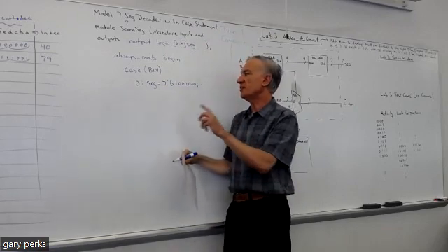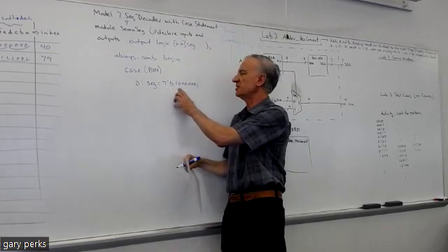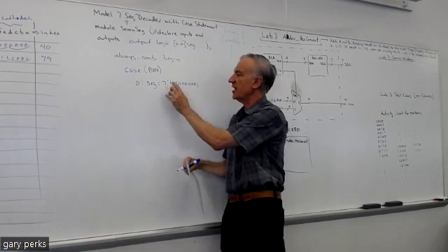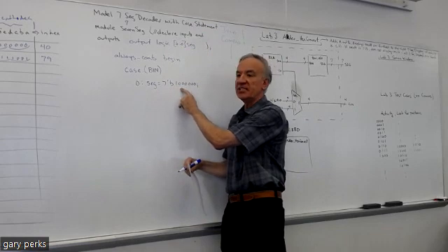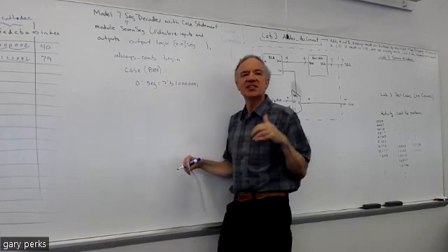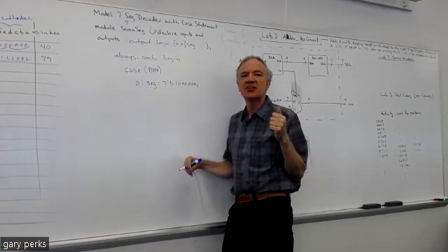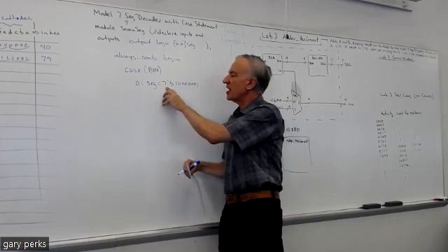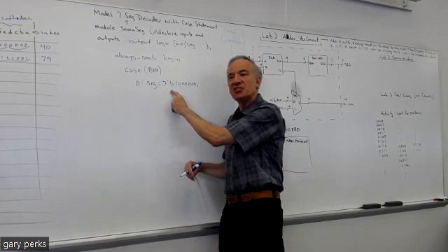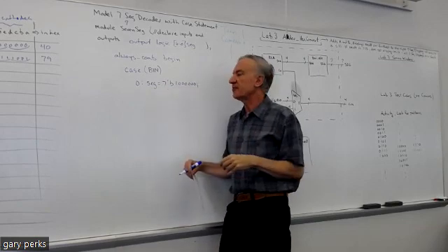Now, instead of doing 7 tick mark B and then listing the 7 bits, you could also do 7 tick mark H and then put 40. So you could put this in hex if you wanted to. But if you do that, it's still got to be a 7. That's one thing that threw me off with Verilog and SystemVerilog: I thought because it's 2 hex characters, it would be like 2 tick mark H40, but when you do that, you get an error.